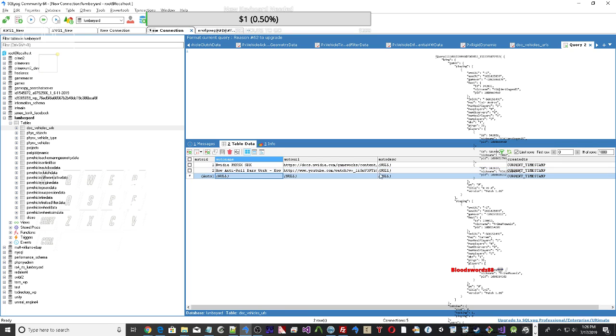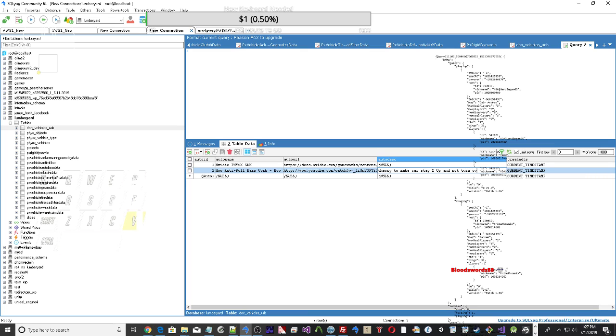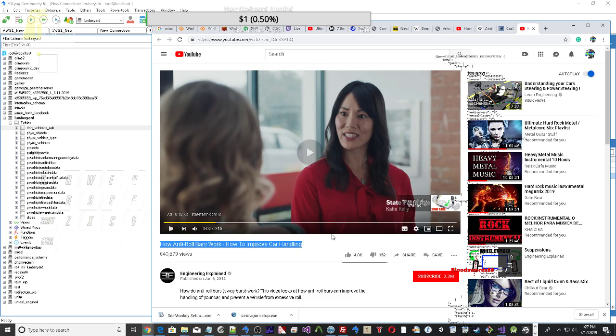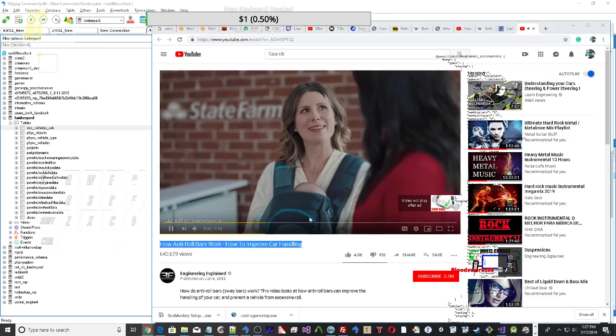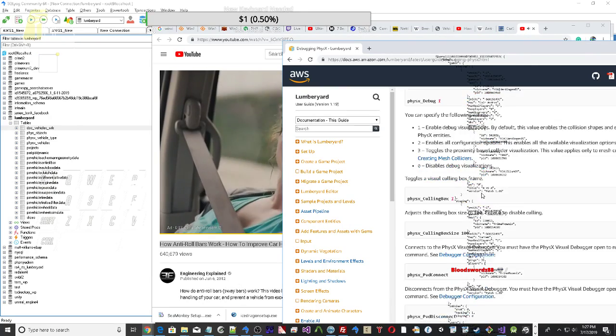The vehicles are updated with the following function call. PxVehicleUpdates(timestep, gravity, frictionPairs, 1, vehicles, NULL). The function PxVehicleUpdates updates the internal dynamics of each vehicle, poses the wheel shapes of the vehicle's actor, and applies either velocity or acceleration changes to the actor, depending on the update mode chosen with PxVehicleUpdateMode. More details can be found in section wheel pose and section vehicle update.